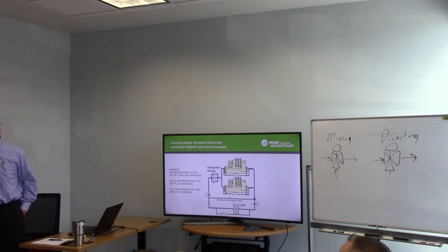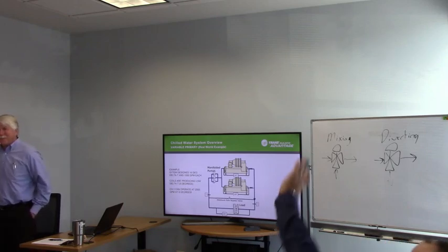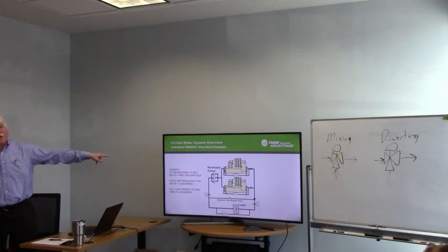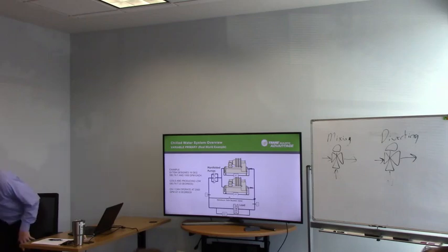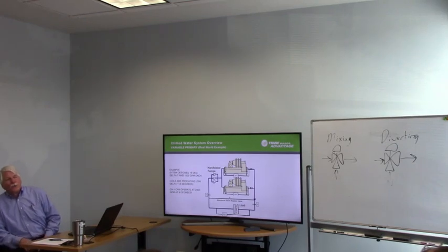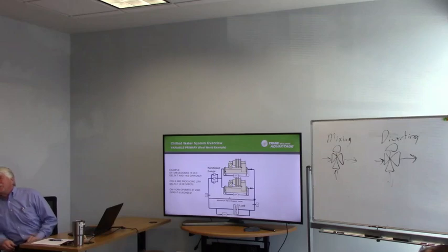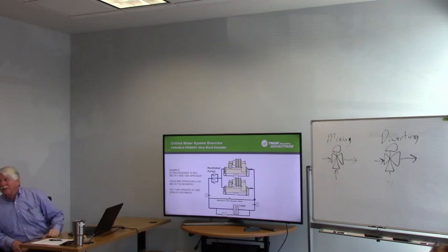Now, how many of you have been to Albany's Candy? This is how Albany's operates. And the reason it operates that way is the way they operate their air handlers. They always leave the coil valves wide open at the air handlers, and we have what's called low delta T syndrome out there. So we're sending cold water out at, I don't know, 38 degrees or something, and it comes back at 42 or 43 degrees.